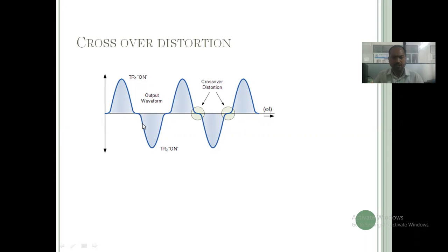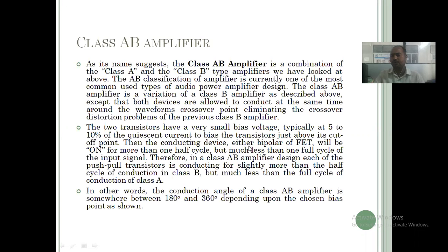So up to this portion, right? Up to this portion indicates that whatever fluctuation or distortion was coming, that is not coming because your transistor is working. Means no transistor should be off. Means we are designing or biasing the transistor in such a way that it should work during the crossover distortion portion also, right? So that's why there should not be crossover distortion coming with respect to the amplifier.